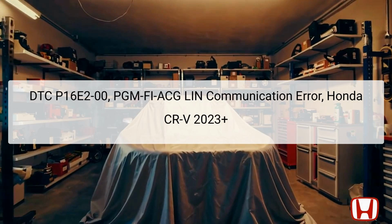The impacted components primarily include the alternator, PCM, and the 12-volt battery sensor. The alternator is responsible for charging the vehicle's battery and providing electrical power, while the PCM is a critical module that manages engine functions and diagnostics. If the PCM detects an abnormality in the received signals from the alternator, it will store the DTC for further